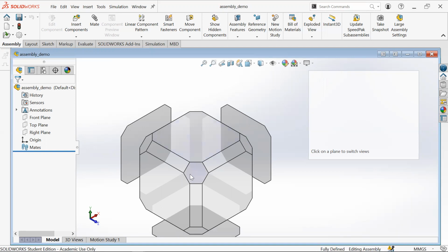Yeah, so if you start building right here, once they place your assembly in your drawing, it's going to be oriented weird, and it might not convey all the information that you want your audience to know. So make sure that you're in isometric view before you start building. So everything gets pulled apart, gets exploded in a way such that you can see all the holes and all the different edges that might come together.